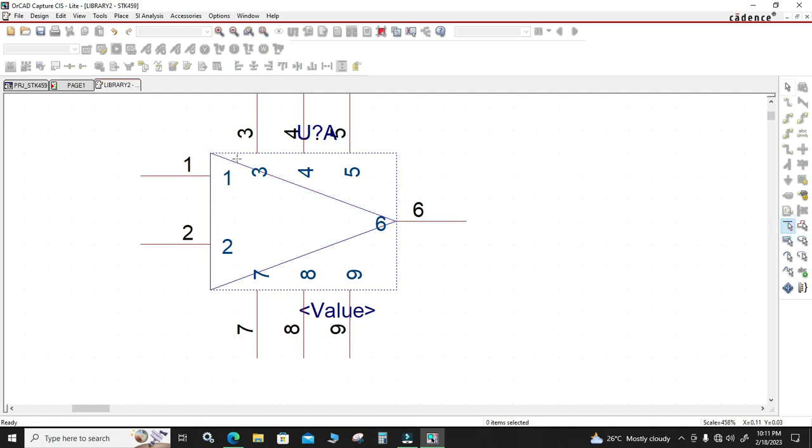For example, we click here and stop here, and click here and stop here. If it is not turned off, the path will only catch on grid points. That is why, when we have to draw smooth drawings, we turn off snap to grid. So we draw like this, like this, like this. Completed.